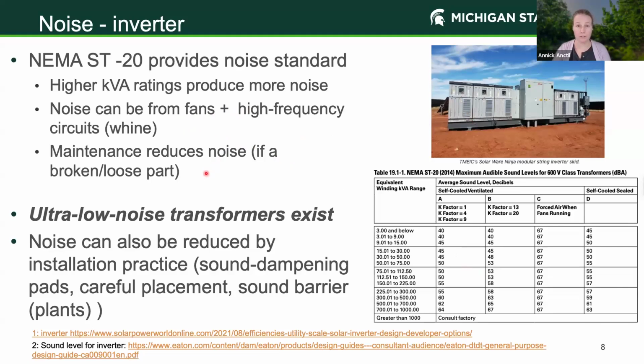In general, noise shouldn't be an issue in solar if you've designed your system properly and planned where you're going to put your transformer versus where people live, the distance to it. And also if you've put pads underneath to reduce vibration, or if you put some sound barrier, but usually just your plans should block most of the noise from the transformer.